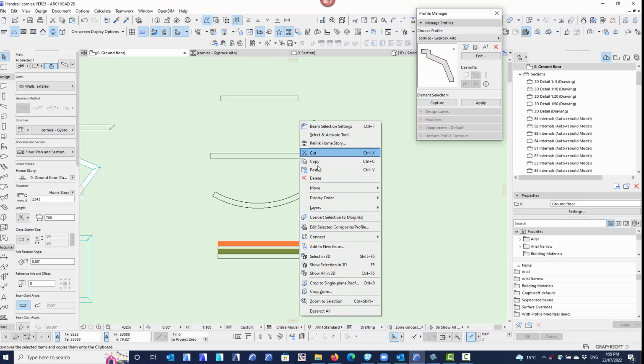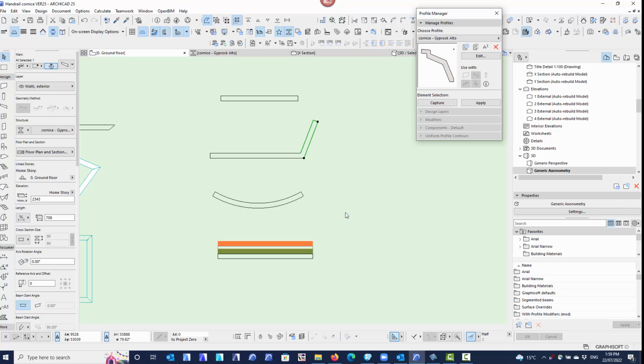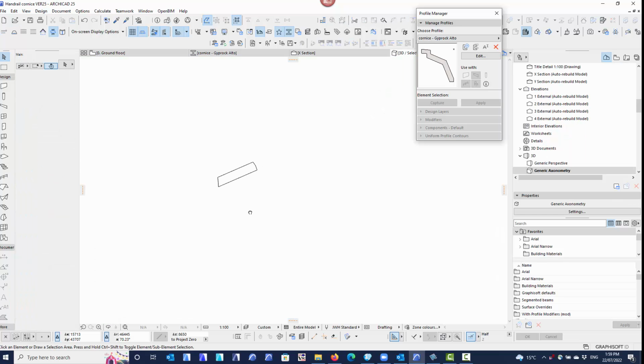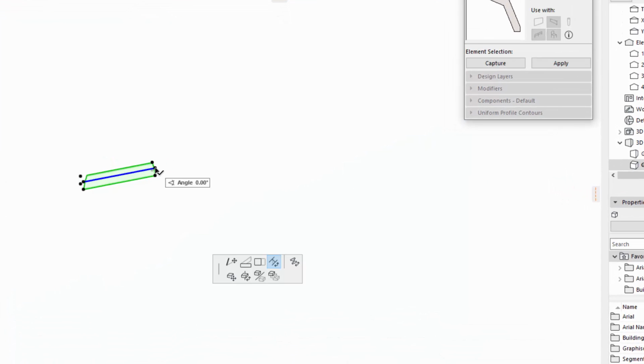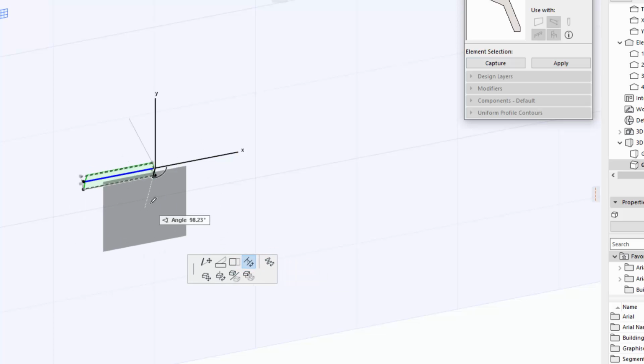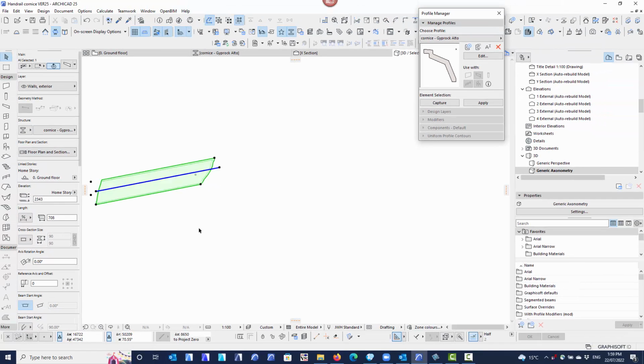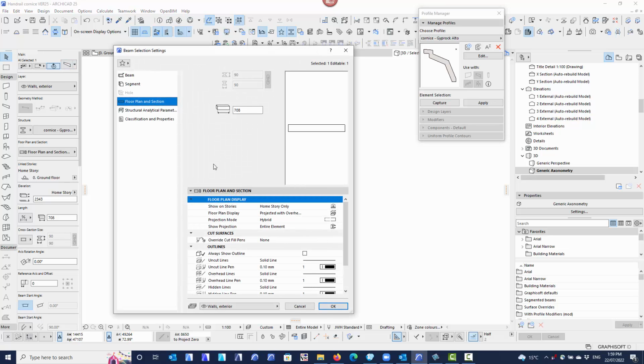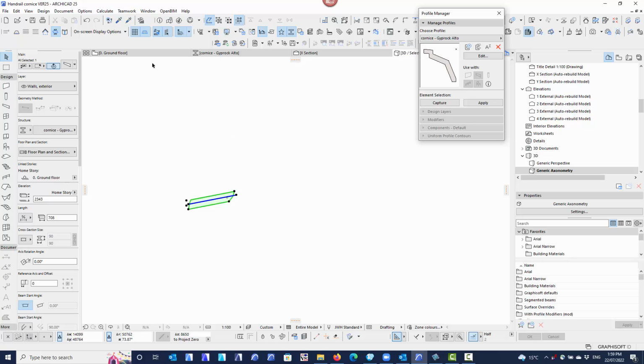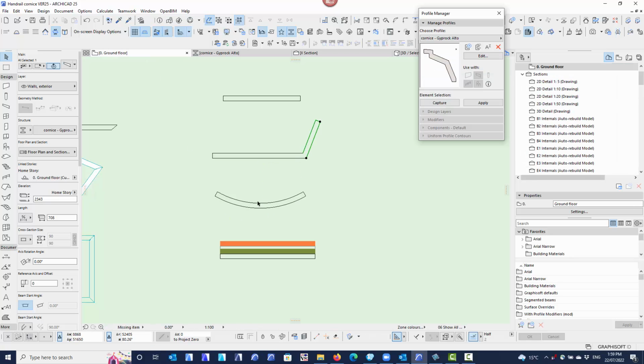So if I was to look at that beam in 3D, you can select it, click on the end, and you've got a pet palette option here for rotating the join angle, so you can actually change the angle of the mitre on the end of the beams, and you can do all sorts of things to get them to join together. But as I say, they should join together automatically when you touch two beams together.